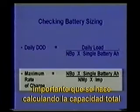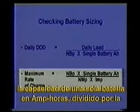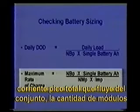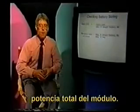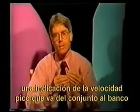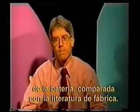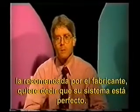You calculate this by, again, calculating the total capacity that you've actually installed, the number of batteries in parallel times a single battery's capacity in amp hours, and you divide that by the total peak current that might be flowing from the array. The number of modules in parallel times the max power current of a module. When you finish doing this calculation, you then have a charge rate that will give you an indication, compared to manufacturer's literature, of the peak maximum rate that might be flowing from the array into the battery bank. If this is slower than the maximum charge rate recommended by the manufacturer, then your system size is just fine.